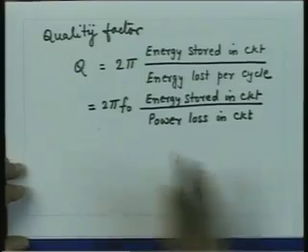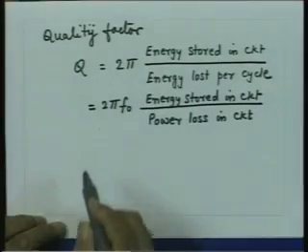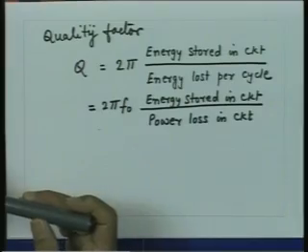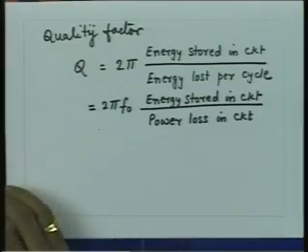Alternatively, as we mentioned, the quality factor is related to the frequency response. So, if I plot the variation of current or voltage when a voltage or current source is applied to the input section of a transmission line and measure the 3 dB bandwidth of the response, the center frequency divided by the 3 dB bandwidth of the frequency response gives me the quality factor.